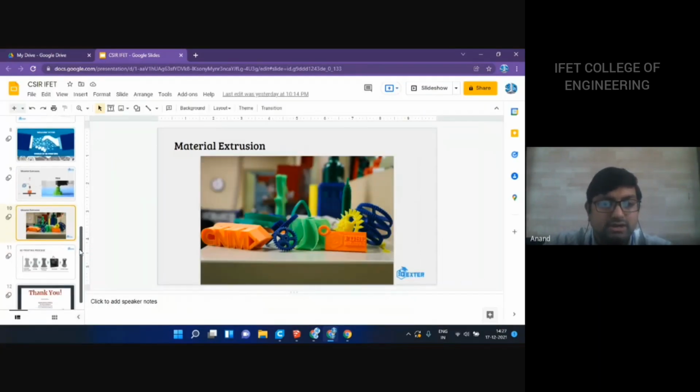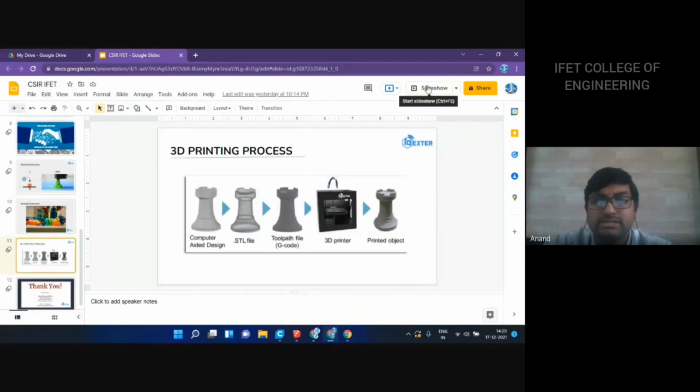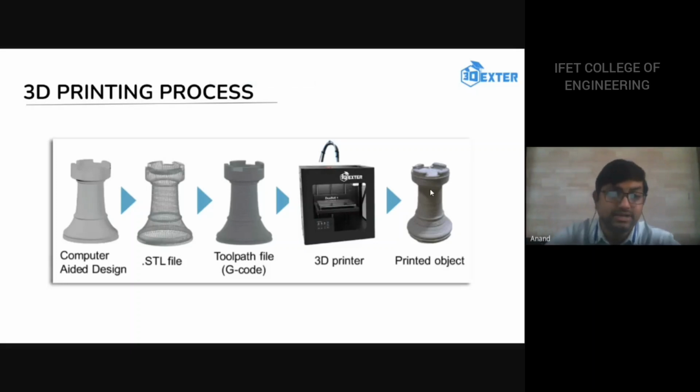So basically, this is the complete 3D printing process. I will be using a CAD software to design something. I will be trying to create a keychain today. After doing that, I will transport it to STL format. I will also try to say why we do that.